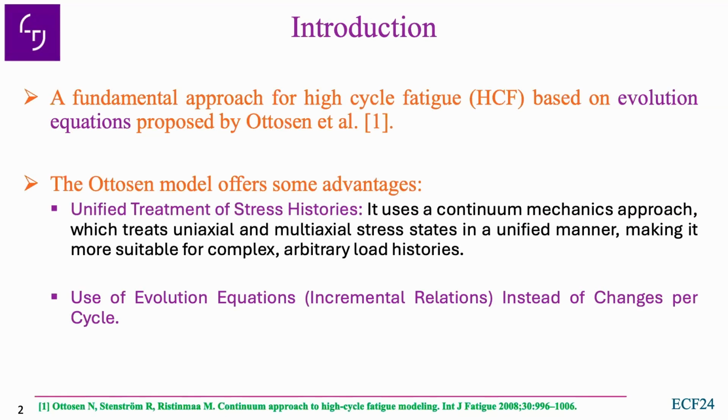A fundamental approach for high cycle fatigue is based on evolution equations proposed by Ottosen and his colleagues in 2008. The Ottosen model offers some advantages in comparison with other traditional methods like rainflow. In the Ottosen model, unified treatment of stress history is used.